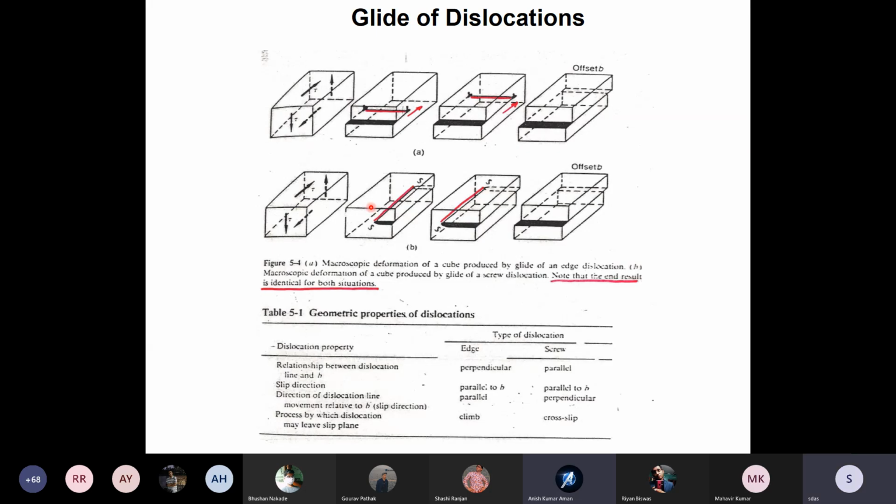About 2 feet. So it already had close to 10 to the power 10 dislocation lines per centimeter square. Because the larger the number of dislocations, the stronger the material will be. So when you are twisting, you increase the dislocation density from 10 to the power 10 to say 10 to the power 12. If you do a little more, it will snap. An easy thing to take is a metallic paper clip, but with no plastic coating on it. You can easily snap it after 8 or 10 twists.